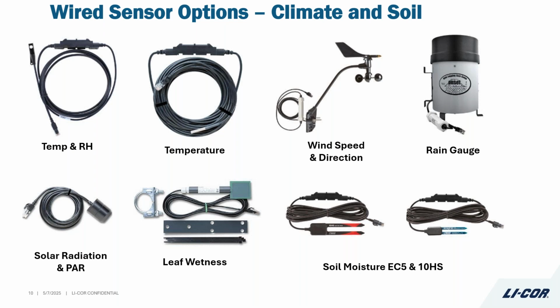They have like the old phone jack connection, and you really just plug these in. There's no calibration needed. These are parameters you plug into the system, turn on the system, and you're already recording data. So we've got these options: the temperature and relative humidity. If you're wanting to do frost alerts or any type of IPM program, you can utilize this with whatever you're looking for. A temperature sensor, if you're trying to use it for operations on, when your employees need to take breaks, if it's over 100 degrees or over 95.